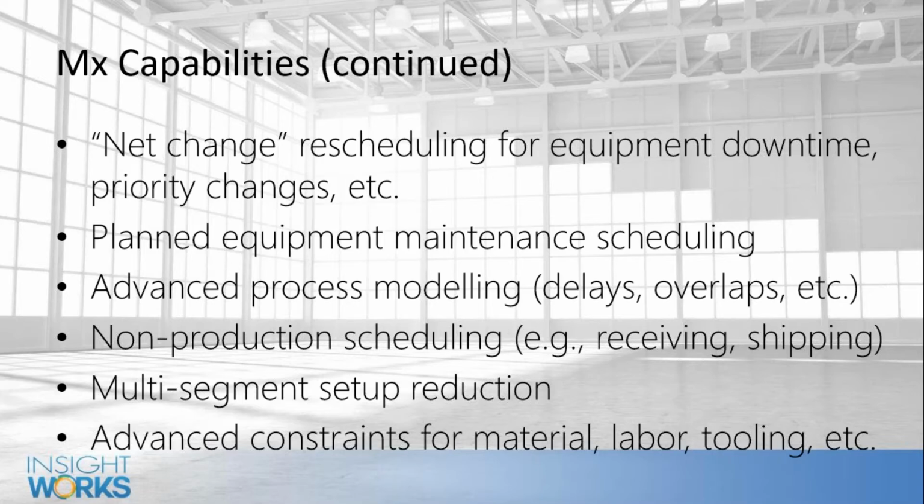So what we can do is if we group those similar items together, we can eliminate that mold changeover. So we eliminate that 2-hour changeover all the time, and we only have to deal with the color changeover, right? And then we can use the sequencing I talked about on the last slide for sequencing the colors, so we can go from light to dark, so we don't have to do massive changeovers when we change colors.